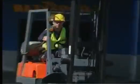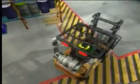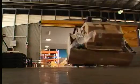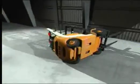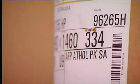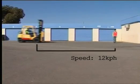The number of deaths and serious injuries that occur each year show that a forklift can be dangerous if stability is not understood. To prevent your workplace from adding to these statistics, make sure you understand the stability triangle and the consequences of forward, sideways, and dynamic instability. Understand load capacity and safe traveling speeds when you operate a forklift.